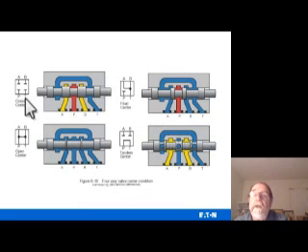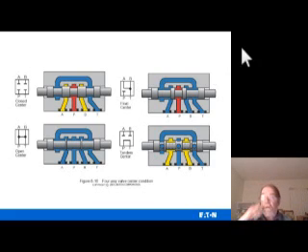This is the same valve where all of them are centered. Then it's moved in one direction, and it's going to just circulate the fluid. This circulates it and blocks the A and B ports, and this one here lets it drain back to both ports, drain back to the tank. I think, yeah, it's a T. Again, the T stands for tank, and P is for pressure. A and B are for the cap and rod end of your actuator.